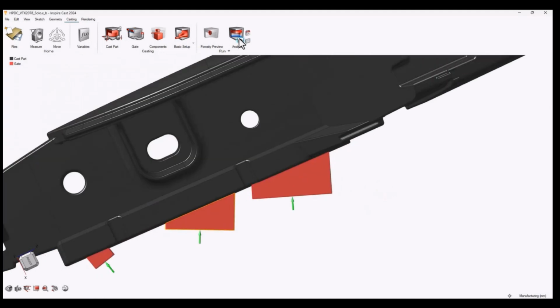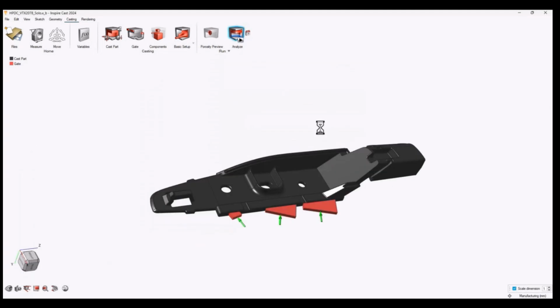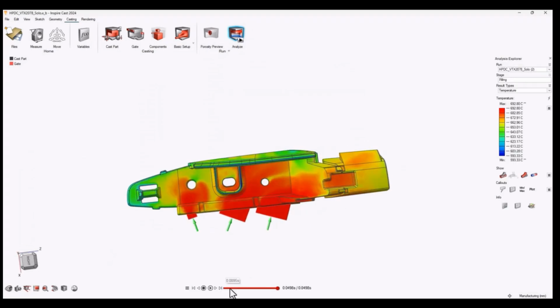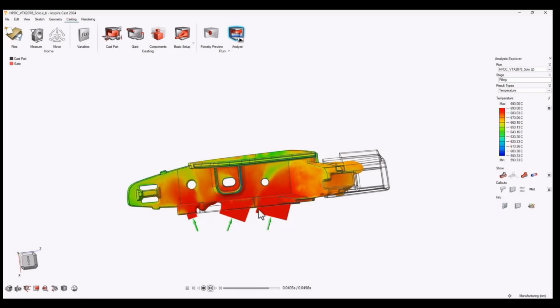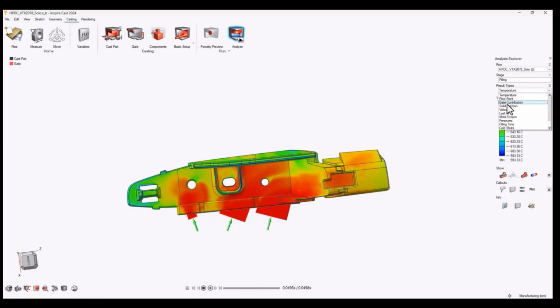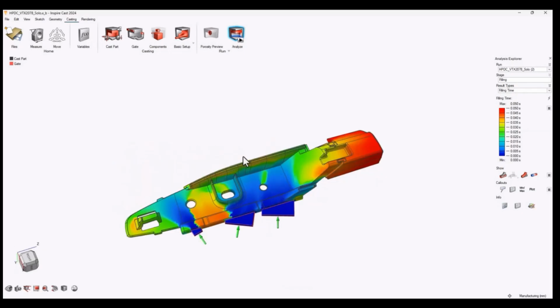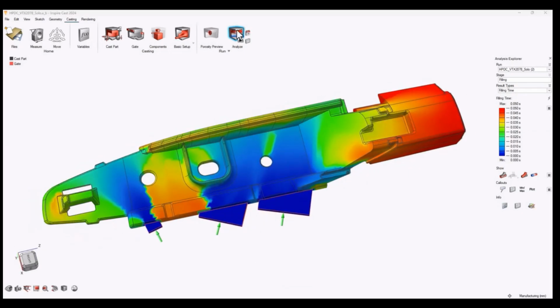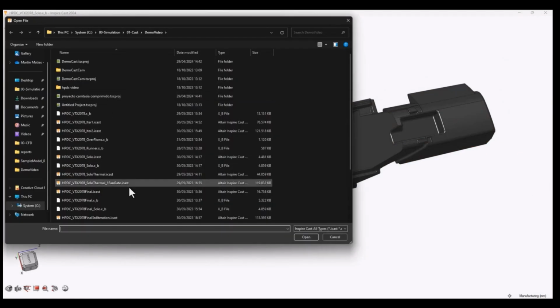So he's trying to manipulate this particular ingate and reanalyzing it. Now as you can see, it is a pretty good flow of metal as the molten metal moves to the right hand corner of the model. It is not turning blue, so it is keeping a certain temperature.